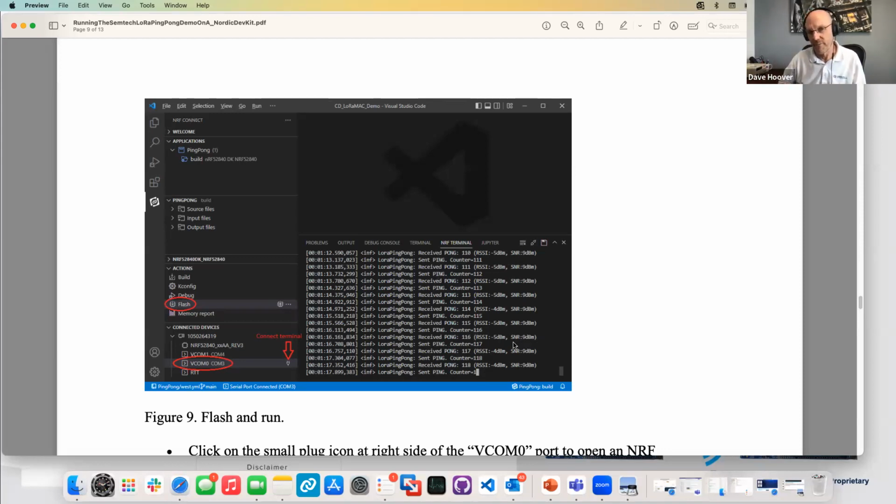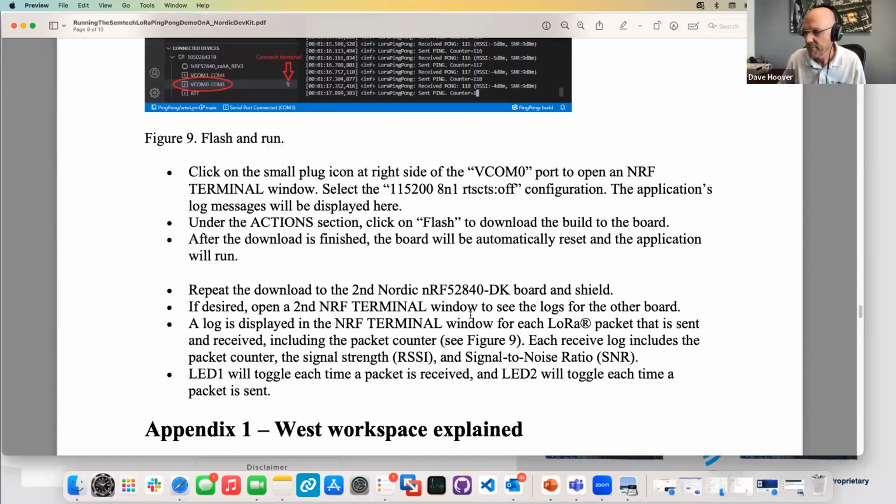As I was saying before, now that you have all of that, you can start walking away while monitoring all this, and you can get a really good sense of how far your LoRa application is going to work, which is hugely important for understanding range. Every customer using LoRa is going to be asking that. That's almost the very first thing they're going to be looking into.